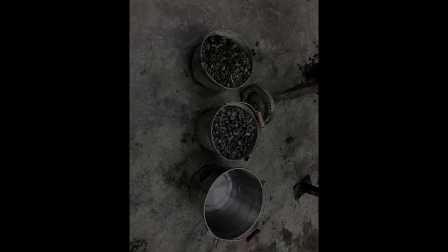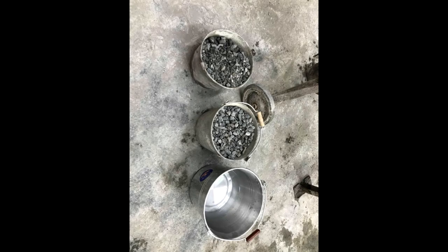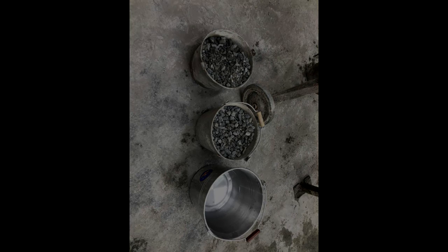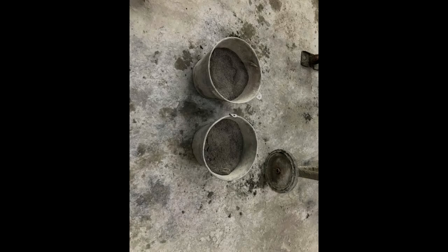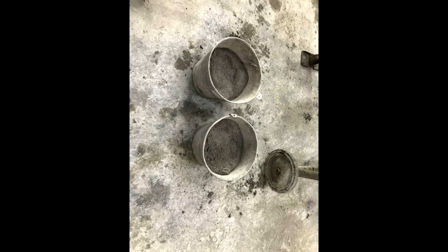of concrete. Trial mixes and fresh properties of concrete are done by preparing a proportioned batch and placing the mixture to butter the mixer. Next is to prepare the amount of fine aggregates, coarse aggregates, cement, and water. Add 50% of coarse aggregate in the mixer, followed by 100% of the cement, and finally 50% of fine aggregate and dry mix for 1 minute.